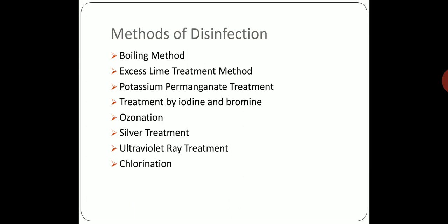Bacteria-laden water contacting the silver releases a minute quantity of silver, from 25 to 40 parts per billion, that is ppb, which serves as a disinfectant. The contact time varies from 10 to 60 minutes. However, since silver is costly, this method may be used only in small installations or for private individual houses.